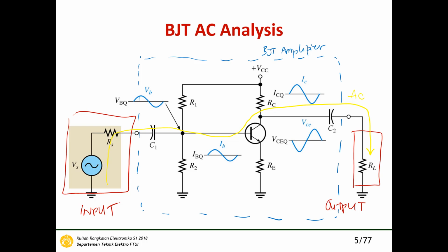So this is the AC signal amplified by this BJT amplifier, and then we control the operation of the BJT using the DC analysis. It's about how much we can amplify the signal. So we can control it by using the DC component. We can change the Q-point, so the amplification characteristic of the BJT will change. We can see here the input signal in the base terminal, IB, and then the output signal in the collector.